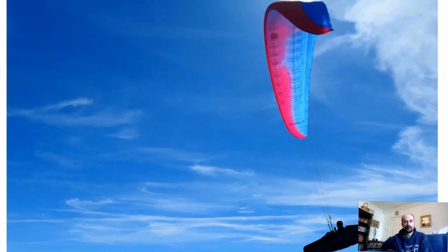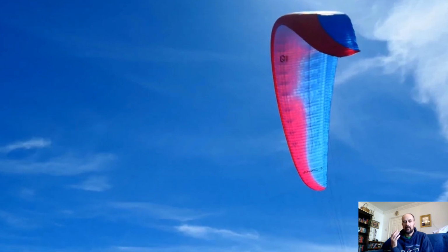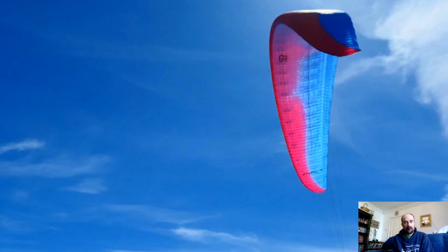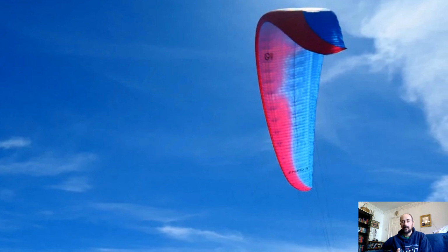There are some real big possible benefits we could get though if we can really optimise the span-wise lift distribution and so minimise the induced drag. You can get a bit of a clue for how big those benefits could be when you look at what paragliders manage to do. Fundamentally, paragliders have to make some pretty serious compromises in their design to be able to work. So you have to have a very big wing area compared to a hang glider, so a lot of wetted surface area.